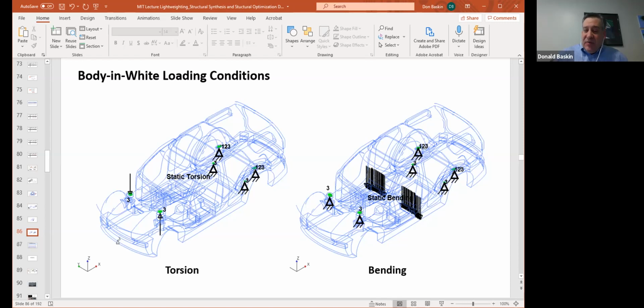We talked a little bit before about single shear versus double shear, a couple lectures ago, was it last lecture? Again, this is something that's very critical in suspension mounting. On a lot of high-end cars, they'll go through a lot of gymnastics to make sure that all the suspension loading points are in double shear.